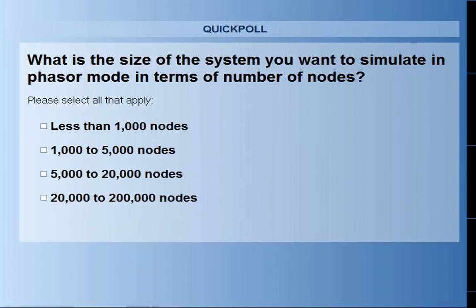The schematics that I gave are for the number of nodes. So if I have a three-phase simulation, simulated in full three-phase mode, you have to consider that we're talking about nodes, not buses. So you would have to divide that number by the number of phases. But having that said, we do offer full three-phase simulation as well.